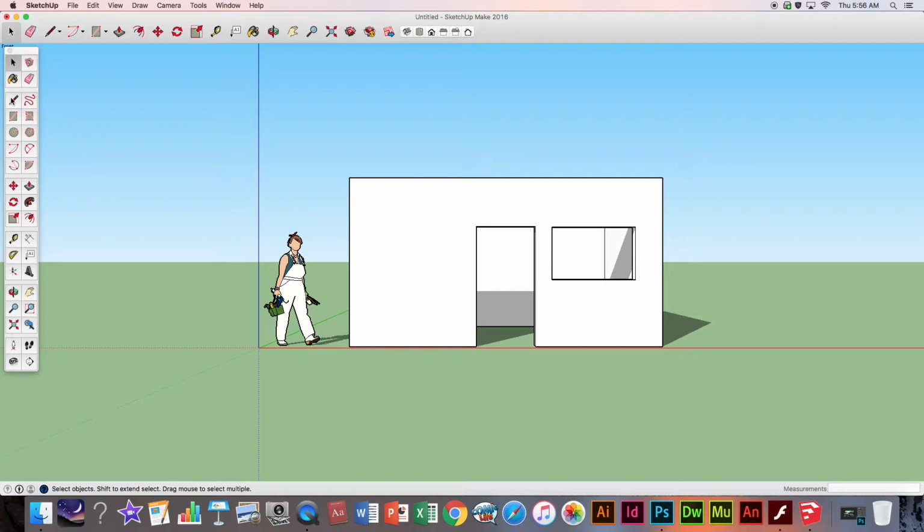Now let's go back to our line tool. You'll notice that it locks into these, which are called the vertices. It calls them the endpoints in this program, but they're vertices, they're points. We can click the endpoint, and you can go approximately in the middle. I could be more accurate, but I'm going to go about there. And now I'm going to go down to this endpoint, click there, and you'll see that it automatically makes a face when it connects. Pretty cool.